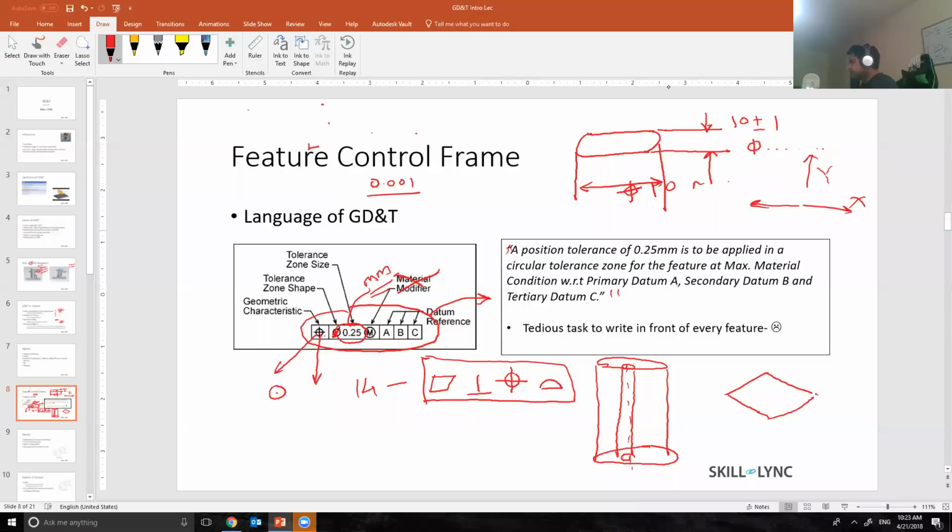Okay. And then regarding the tolerances, diamond pin is nothing but a gauge pin. So if I have to check this slot over here on a hard gauge, what I would do is I'll create a diamond pin. I will have this size as the virtual condition. Again, this virtual condition, we are not going to discuss today, but for today, just assume that we have something called a virtual condition concept for every tolerance.